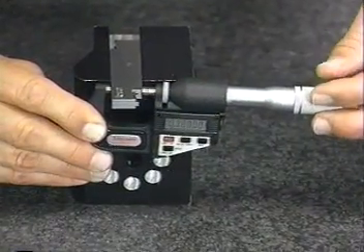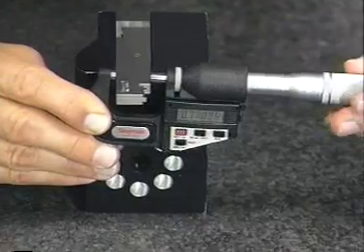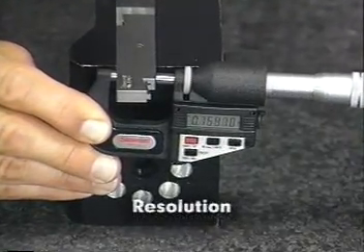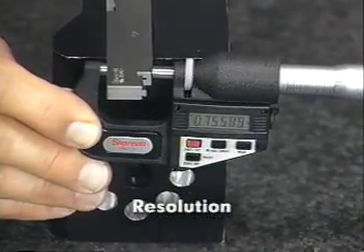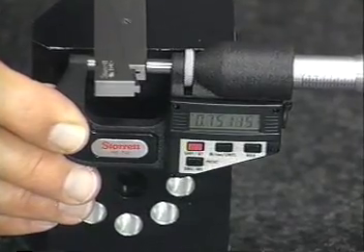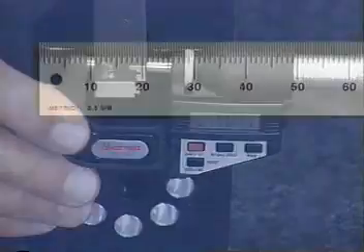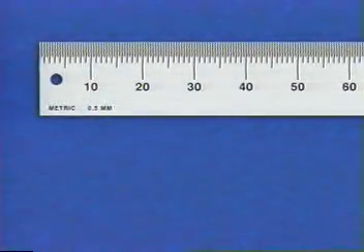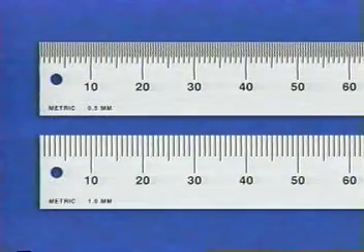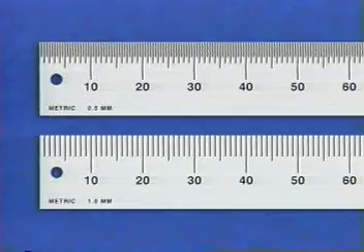The precision of a measurement device is in part a function of its resolution, which is the smallest graduation into which an instrument is divided. For example, a rule marked in 1/2 millimeters has a higher resolution and thus can be more precise than a rule marked in millimeters.